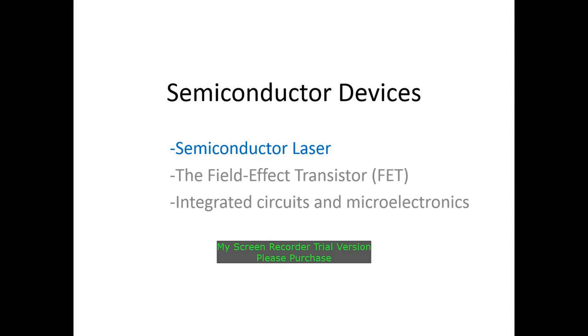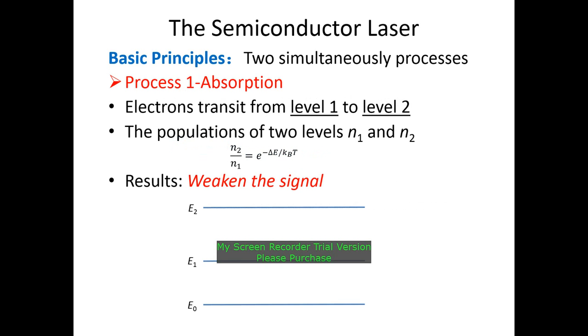Hello everyone. Continuing James' presentation, I'm going to introduce more semiconductor devices. The first semiconductor device I will introduce is the semiconductor laser. To illustrate the principle of laser generation, let's consider a box with gas, and we can just focus on two of the excited energy levels, I mean the first two excited energy levels, the lower energy level E1 and the higher energy level E2.